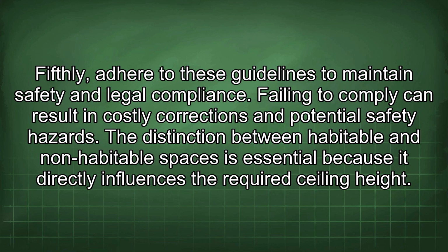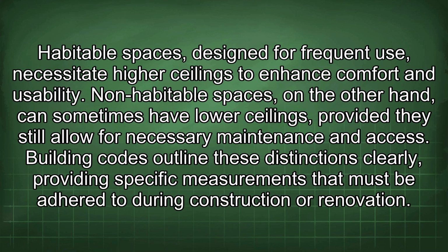The distinction between habitable and non-habitable spaces is essential because it directly influences the required ceiling height. Habitable spaces, designed for frequent use, necessitate higher ceilings to enhance comfort and usability. Non-habitable spaces, on the other hand, can sometimes have lower ceilings, provided they still allow for necessary maintenance and access. Building codes outline these distinctions clearly, providing specific measurements that must be adhered to during construction or renovation.